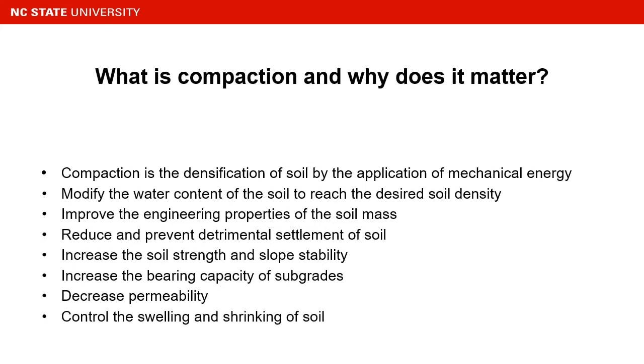So what is compaction and why does it matter? Compaction is the densification of soil by the application of mechanical energy. Think filling a bucket with sand and hitting the top with your shovel. You also have to modify the water content of the soil to reach the desired soil density. Think adding water to that sand so it sticks together better.